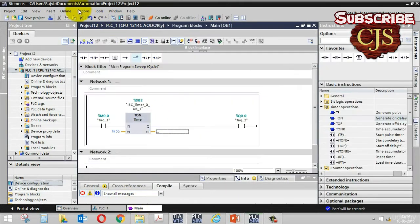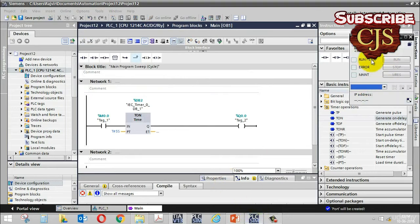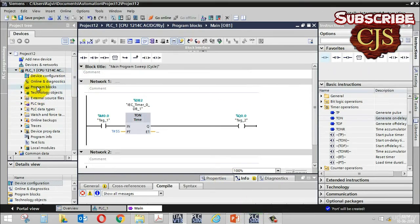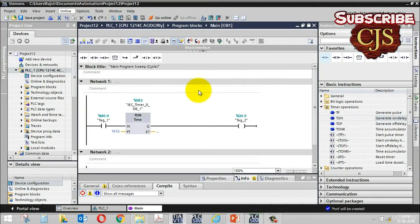The next step is you have to go to online simulation and start. Before coming to start, you have to make sure your PLC simulator is on and you have added your hardware. If you don't add your hardware, the start will not come. So click on start, and it will try to link your simulation with this software, Siemens TIA. So it will link PLC SIM and TIA V13. Okay, so it may take a couple of seconds to interface these two software together, so you should have patience and let the software do its task.